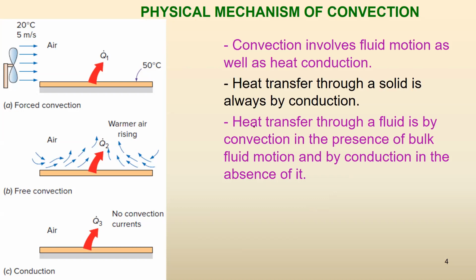Then, as a result of motion that is called advection, the combined mechanism is called convection transfer. So advection is the motion of the fluid, which can be forced or natural, and conduction at the surface, at the interface between fluid and the solid material.